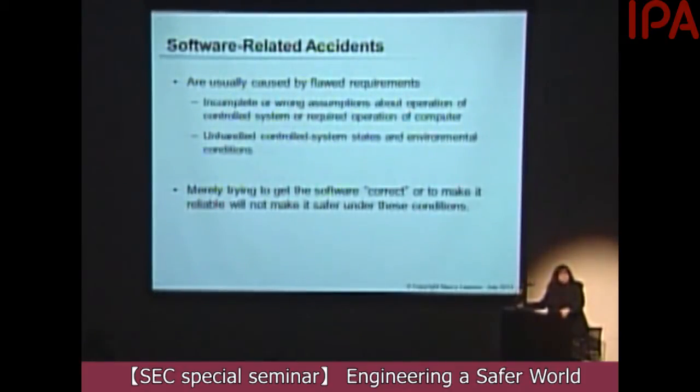How did it know it reached the surface? Well, there were some very sensitive sensors on the landing legs of the spacecraft. And these sensors gave a signal when the spacecraft had landed. It turned out nobody, though, told the software engineers that when the spacecraft was coming toward the planet, to slow down, there was also a parachute that was deployed. When the parachute deployed, there was a jerk on the spacecraft, which caused the sensors to give out a signal.